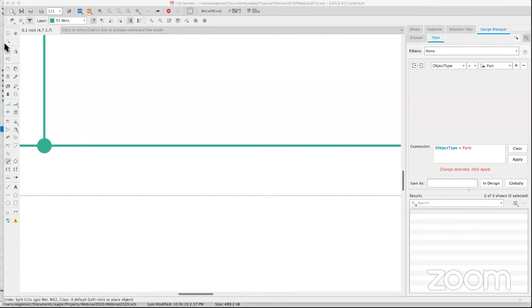Anyway, he's having issues when he takes it into Fusion 360. He says it looks weird. The components look okay, but the board looks weird. I wasn't 100% sure what the issue was with the board. To be honest, on the link that he's giving us, I see no silk screen at all. So I'm going to imagine that this is his Fusion render. That's what I was thinking too. Are you sure that you're using the appropriate silk screen layers, Varga? Make sure that you're using the tNames, the tValues layer, and just make sure that you're using the appropriate layers.